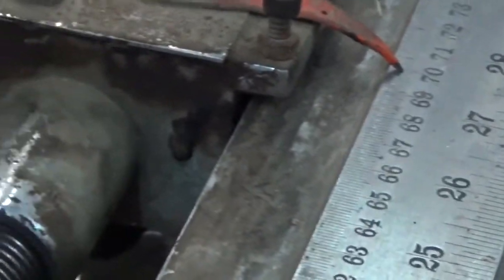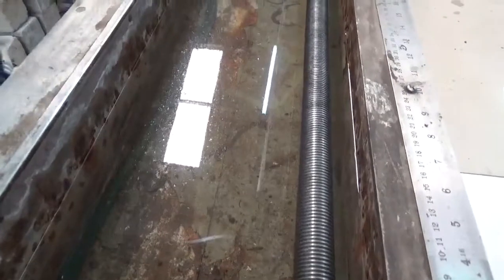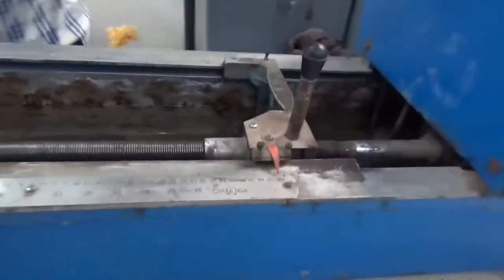A very fine wire is now forming from this bitumen sample. Approximately 70 to 71 reading is reached. Almost the reading has reached up to 95. We are going to stop this machine right now. My sample is still intact. If you see, the fine wire is made of this bitumen sample and still it is not broken. So we can say our ductility is around 95.